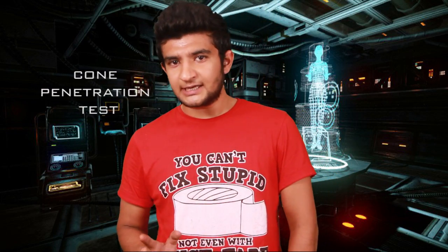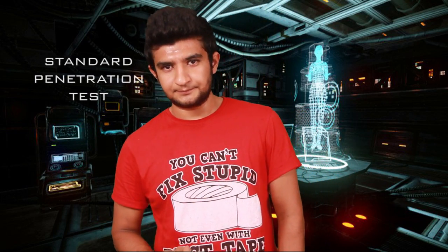Well, as we discussed in our previous film, bearing capacity simply refers to the pressure that a soil can bear at the base of the foundation when the foundation fails in shear. To determine the bearing capacity, the commonly used field tests are the plate load bearing test, the cone penetration test and the standard penetration test.